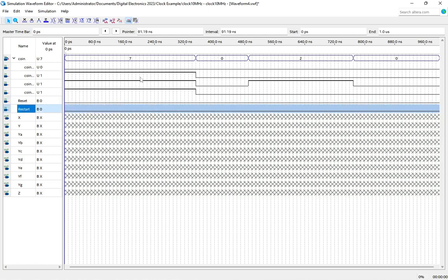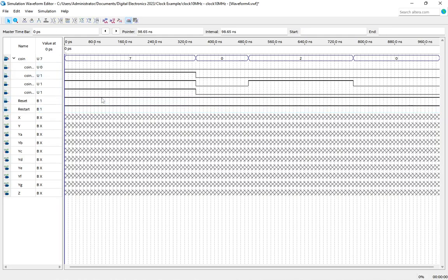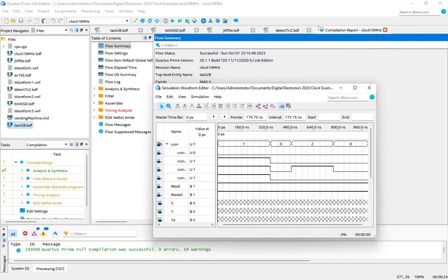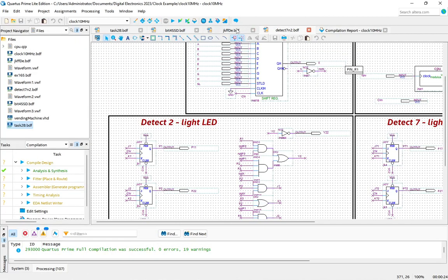Obviously, this is going to depend on your design. But since we are going to be using switches, that means when we press the switch, it goes to ground. You should accommodate this in your designs.